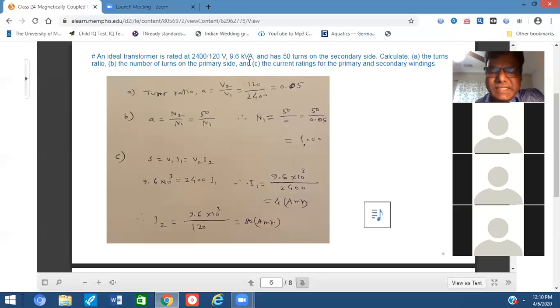And you will be noticing, although we will elaborate on it in the energy conversion class, that a transformer is always rated in terms of kVA, or volt ampere. Never ever will you see it expressed in kilowatt, megawatt, gigawatt or watt. You all know that power is expressed in watt, kilowatt, megawatt, but a transformer is rated in volt ampere, like in this case kVA.